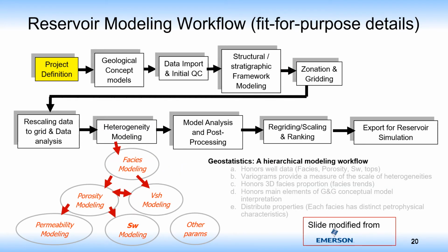So the reservoir modeling workflow, if we lay it out in a sequence here, we define our project, our concepts, get our project set up, define structure and the framework, set up grids and reservoir zones for modeling, scale the data, rescale that data, analyze at various steps, and then we get into the heterogeneity modeling. And as stated, heterogeneity is that combination of the facies and the various parameters.